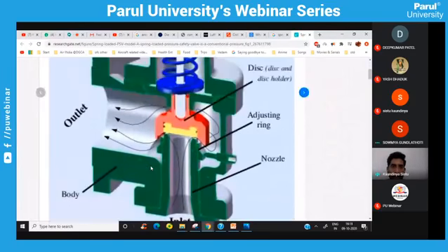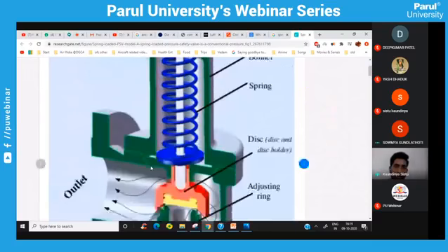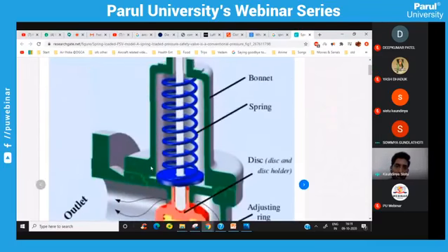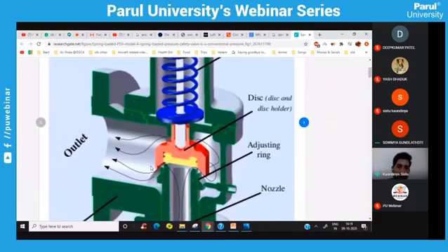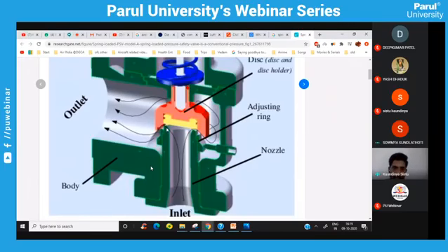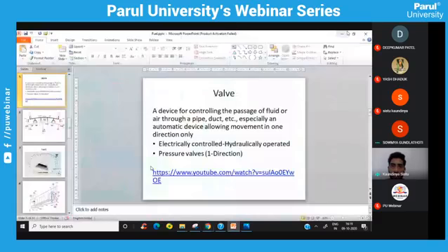It pushes the door up, and then it can go past the spring, to the left side. Door is up. If it doesn't have a certain pressure, the spring will close the door and it will be sealed here, and air will be stagnated here. Only once the fluid overcomes this spring force will it go through from here. So pressure and force go hand in hand always, because pressure is nothing but force per unit area.